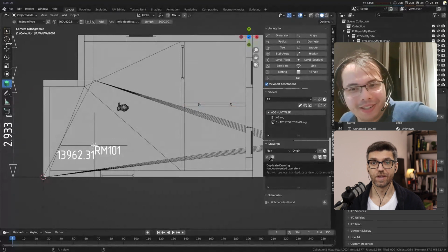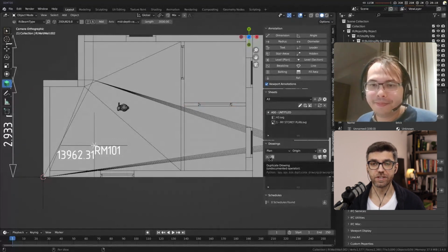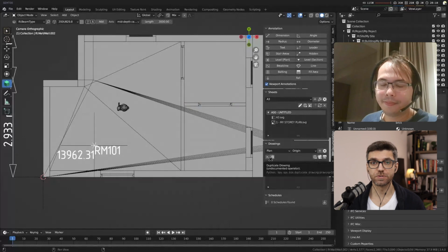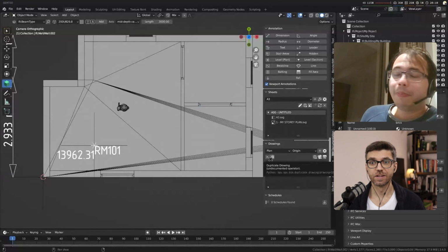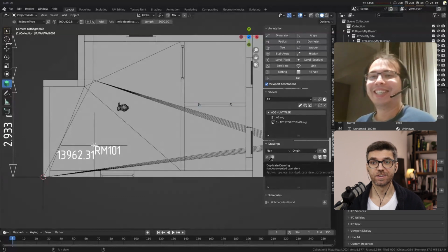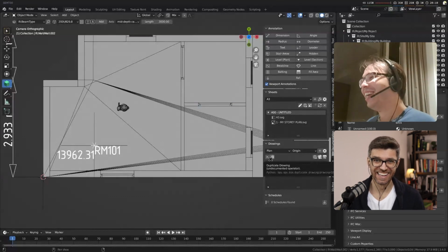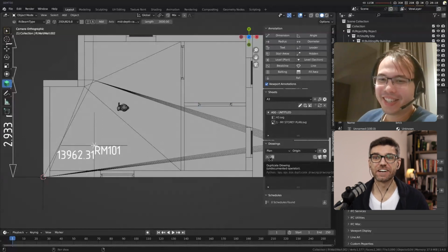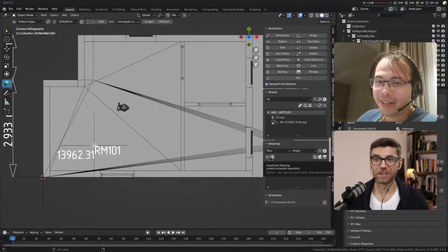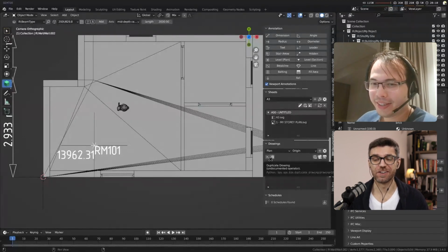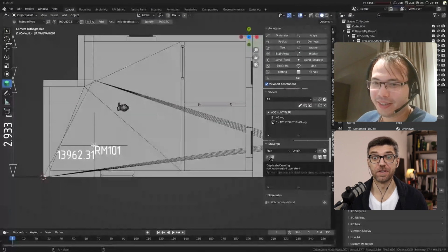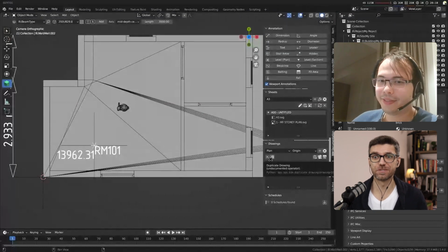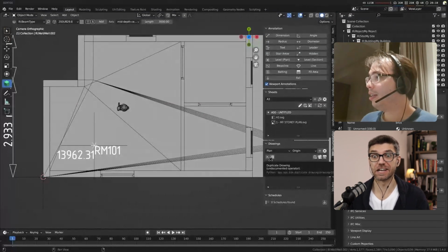And the commands, is it easy for somebody to make their own scripts with Blender BIM operators? Whoa, you're speaking to the wrong person because I'd say sure, but somebody might disagree with that. Like a four line piece of code that says import bpy, import... I don't know how you would import Blender BIM in there, or if it is loaded, I guess it's already part of bpy, right? So then you say bpy.ops.bim.make_drawing or something like that.